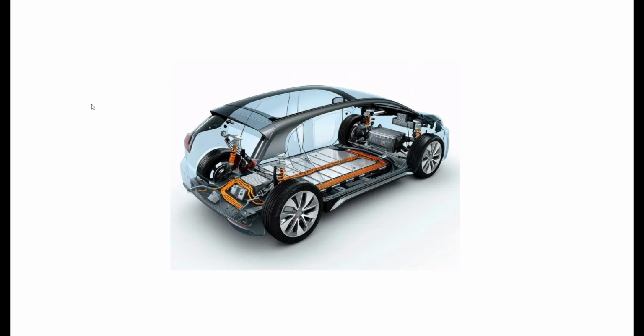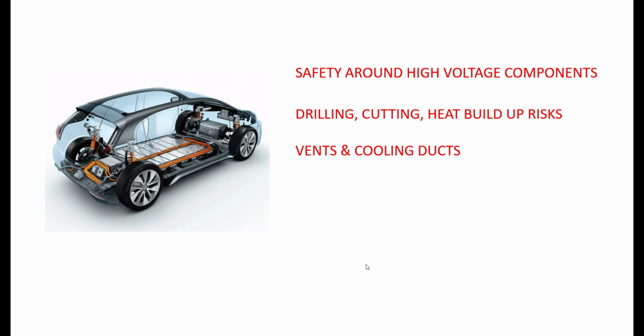So the other thing we want to talk about with EVs and hybrids, which is different to traditional cars, is installation. That's once again because the car's laid out differently, with the batteries and the wiring and everything to do with an electric vehicle, for example. So one of the things when you're doing installs is you need to be careful, because there are high voltage components.